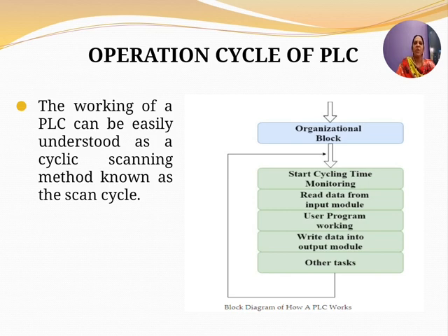The working of a PLC can be understood as a cyclic scanning method known as the scan cycle. There is a method called scan cycle, your organizational block. You can see in the flow chart how the PLC works: start cycling, time monitoring, read data from the input module, user program working, write data into the output module, and do the other tasks. Again it is repeated.